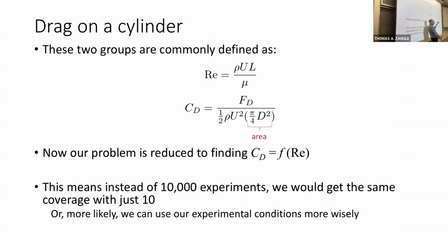Another thing to take away from this is that generally the thing that's on the left-hand side, the variable we say is a function of other things, we normally reserve as a secondary quantity. So we normally make a non-dimensional quantity out of that. You can get a solution even if you don't, but we normally say the thing on the left-hand side is a secondary quantity, so we don't choose it as a primary quantity. And then we're going to end up with that thing as a function of the other non-dimensional variables.